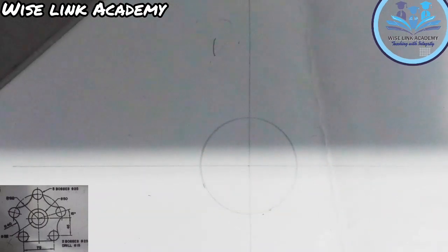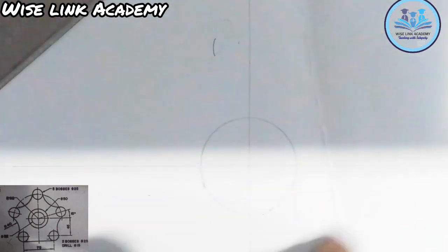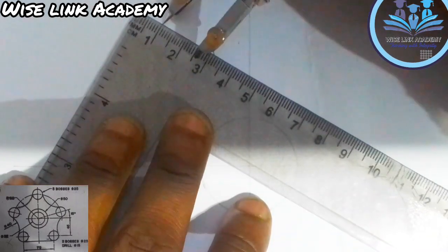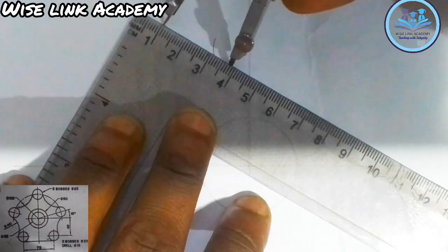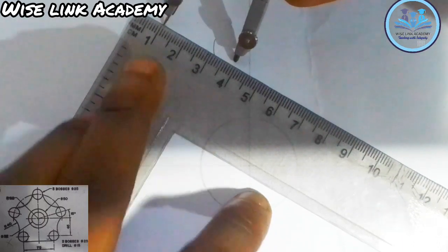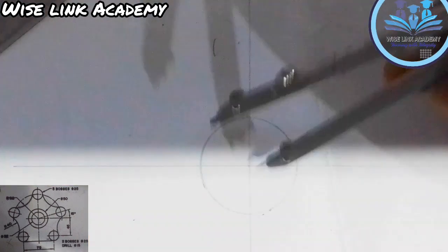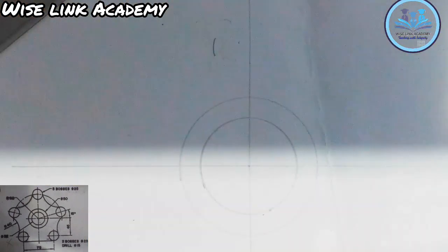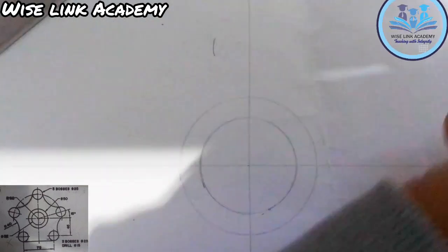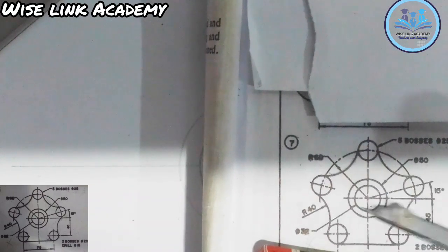Now, the next thing to do is to draw the outer one too, which has a diameter of 50. So let's do that. That's 25 from here. I point 0 to this. 0, 1, 2, 25 is here. So we take it to the center point here, and we draw a circle. We'll be having this. Now I've established this circle here, you are seeing the middle one here is this circle here. But what do you observe?